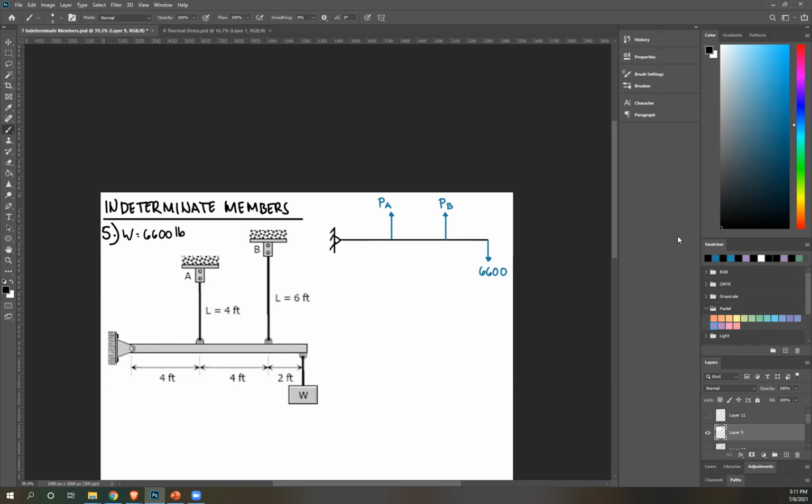Okay. All we need is an equation relating all of our unknowns. Okay. Now, the reason why we can't do summation of forces vertical or horizontal is because there's going to be a reaction here. Right? Let's call this AV, point A, and then AH. Okay? As you can see, if you do summation of forces vertical, we have 3 unknowns. So to get the least amount of unknowns possible, we'll use the equation for moment. So summation of moment, and then we'll take it about the support to cancel your reactions. So about A equals 0.